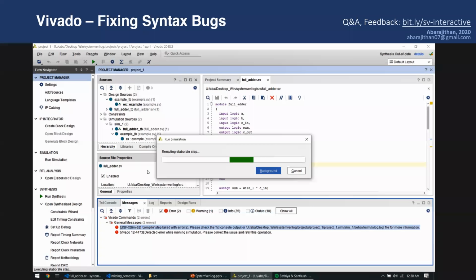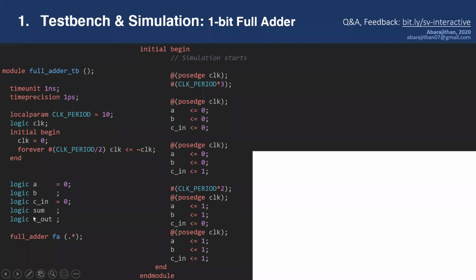Yes, you can use the neg edge as well. So instead of posedge, we can say negedge, but we usually do things on the posedge, and we usually don't mix both posedge and negedge. There are certain cases where we mix both. For example, DDR. DDR is the RAM. It works on both edges. But when we design stuff, usually we don't mix both, because it leads to confusion as well as some other problems. So we use only posedge, but you can do it, of course.